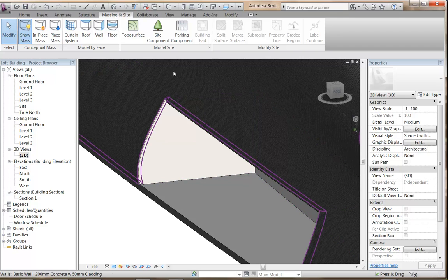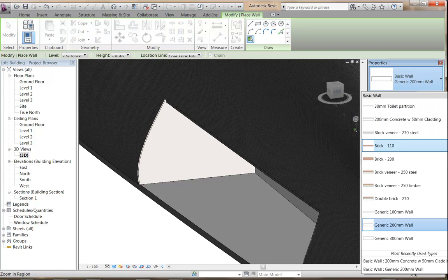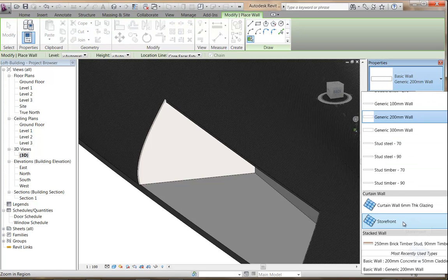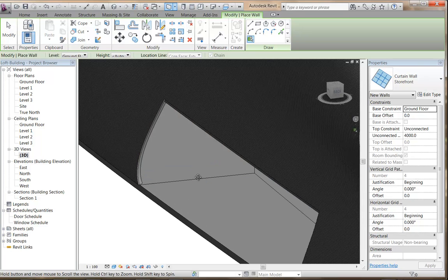Anyhow, here I just put another wall on now, just to show you a different approach to making a curtain wall. I use a different kind here, one that's set up slightly differently, because it should work on that pretty easily. So, right, that'll do for my exterior shell.